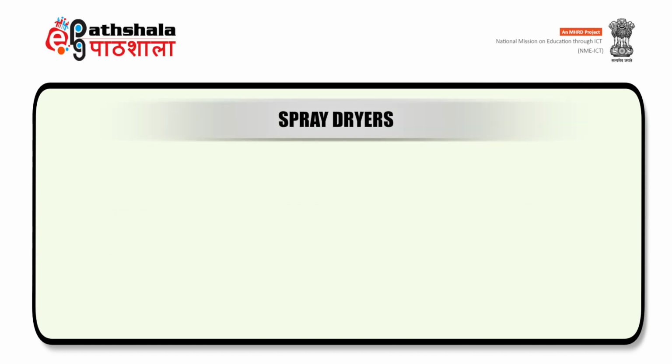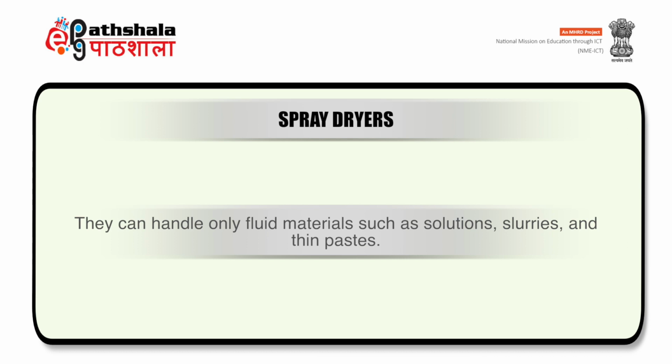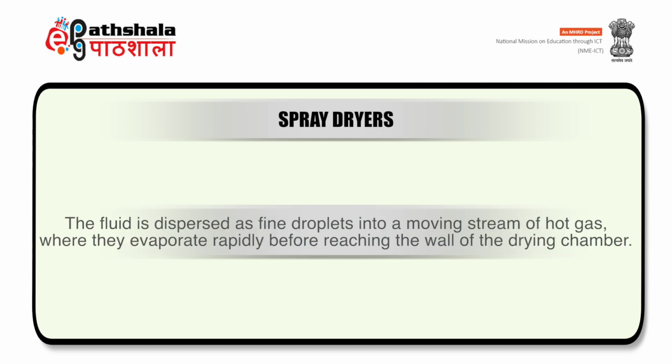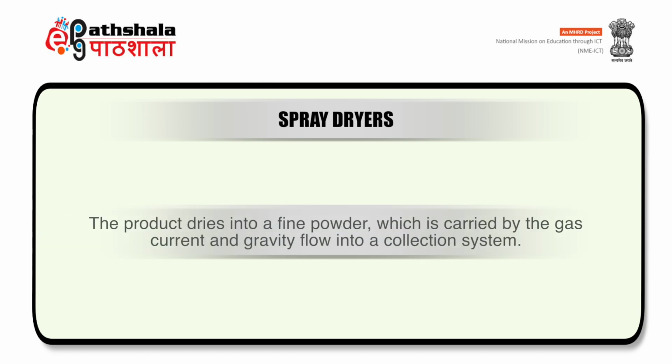Now under pneumatic dryer we will discuss spray dryers. Its principle is they can handle only fluid materials such as solutions, slurries and thin paste. The fluid is dispersed as fine droplets into a moving stream of hot gas where they evaporate rapidly before reaching the wall of the drying chamber. The product dries into a fine powder which is carried by the gas current and gravity flow into a collection system.